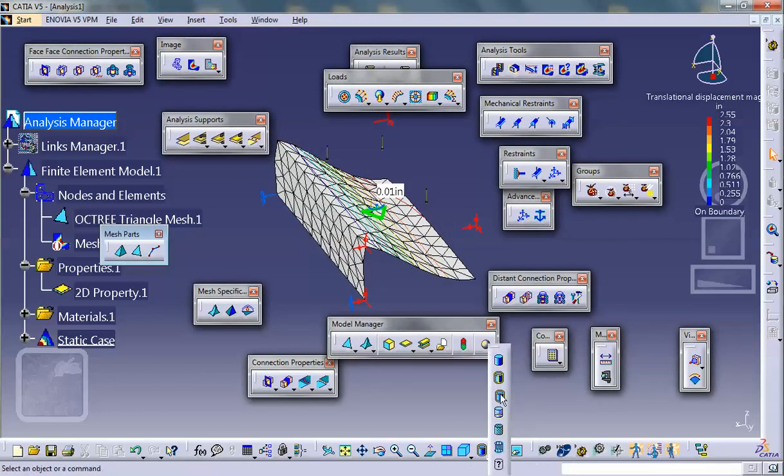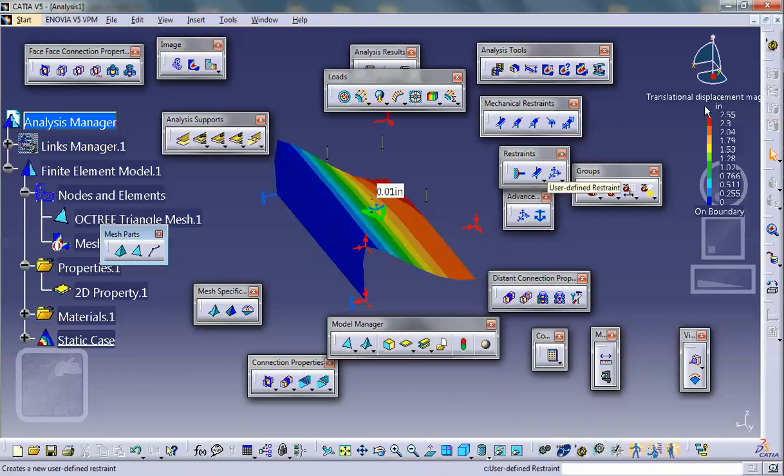Now, this is a huge deflection. It's impossible to have an elastic response of 2.55 for the size of the geometry that I gave you. Keep in mind that this left edge is only half an inch. And how can the deflection here at the center be 2.55 inches? That's impossible. Which means that Catia will do what you ask it to do, but it may not be meaningful.